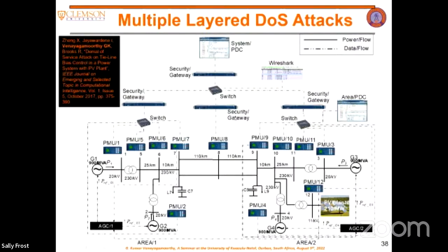So in the lab, we modeled not only the power system, but also the entire communication network. All the security gateways and all the switches, all the data flow, basically all that has been modeled in real time on the RTDS, real-time digital simulator. And we also have a 210 megawatt PV plant. This PV plant is dynamic in the sense that this is done at Clemson. So we use the Clemson weather, solar irradiance, to power the simulation of the PV plant. So if there's a cloud cover over the lab, the production of the PV plant will drop. And if you had a great 900 watts per square meter irradiance, then it will be like 180 megawatts production of this plant. So it changes with the cloud. So we can do a real-time simulation, truly real-time, without having a 210 megawatt PV plant. It's modeled, but driven by the actual weather.